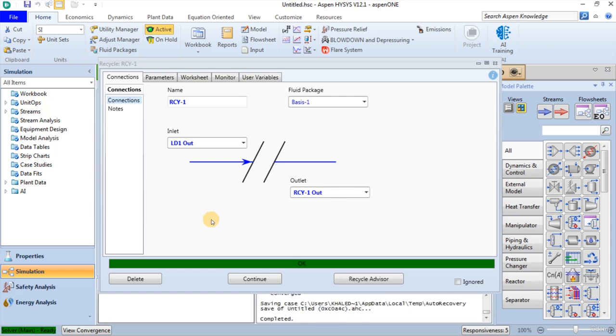The actual tolerance of the recycle operation is calculated as the product of the initial tolerance for the given property, which are fixed values within Aspen HYSYS, and a sensitivity value which is specified by the user. Whether the tolerance used is an absolute or relative tolerance is dependent on the specific property in question, and it's set by the Aspen HYSYS program.